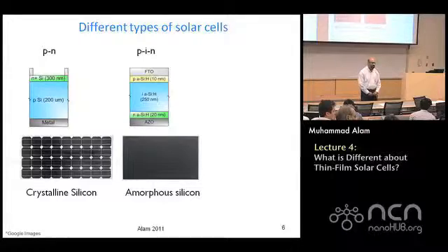The main reason for thin film, as Professor Lundström also mentioned, is that it can absorb light within a very short distance. So gallium arsenide, a few microns is all that you need in order to get 90 to 95% of the light in. Now, remember the 50 bounces that I told you about, it is not on all wavelengths. The wavelengths that are close to the band gap are the most difficult to absorb.